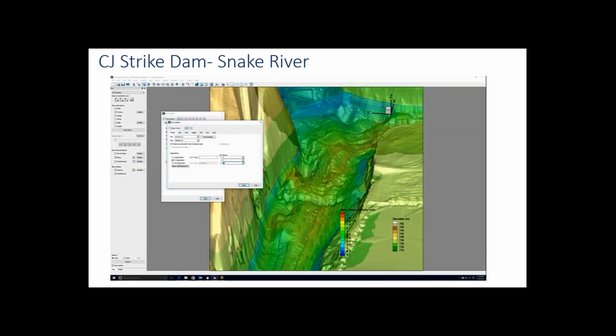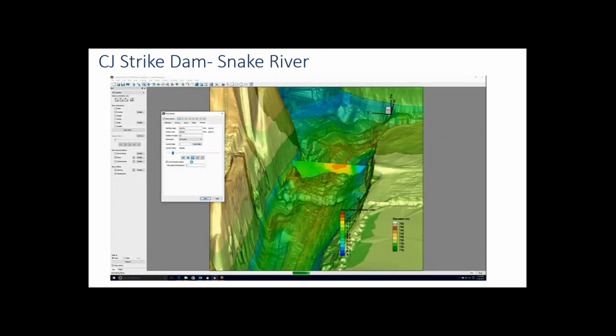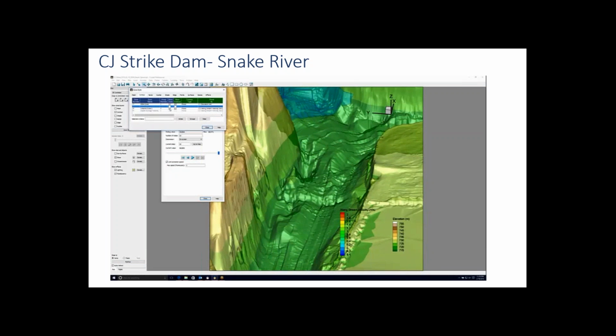A little bit further zoomed in here, some of the scour things show up a little bit better. We've got a little bit of change in the ratio here. Again, you'll see some of the high velocities where we've got these scour holes and so forth. And we'll talk more about this a little later. We can do our slices in any direction. From an arbitrary plane, you can specify the coordinates, X planes, Y planes, Z planes, which are horizontal planes.